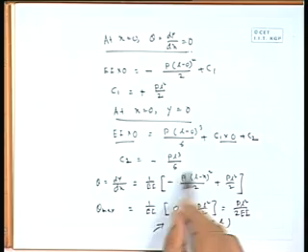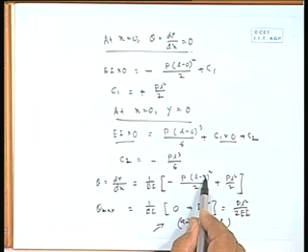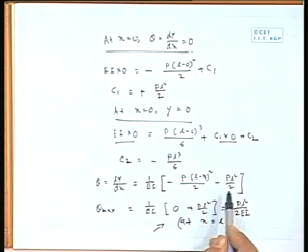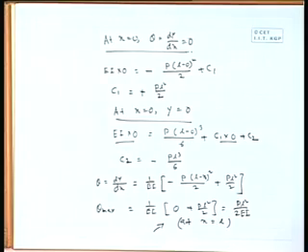So, this term is becoming 0. Say x is equal to L. But we are calculating theta at x, theta at x equal to L. But when x is L, that is the end slope, the maximum slope. That will be P L square by 2 EI.